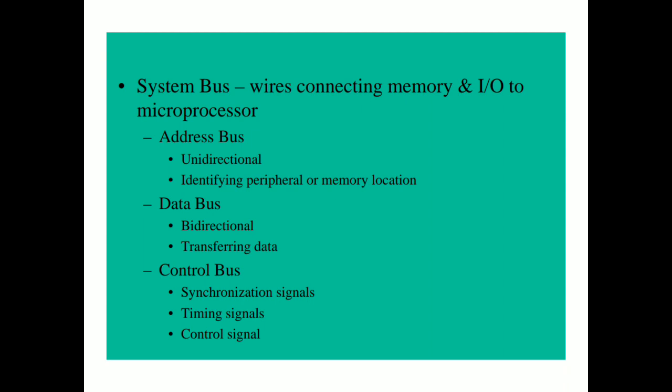So here I have used a new term, program counter. Let me introduce you what is program counter. Program counter is one of the most important registers in the microprocessor. As we all know, program is a series of instructions stored in the memory. These instructions tell the microprocessor exactly how to solve a problem. So the program counter gives the address of memory location from where the next instruction is to be fetched. So it stores the address of the next instruction.